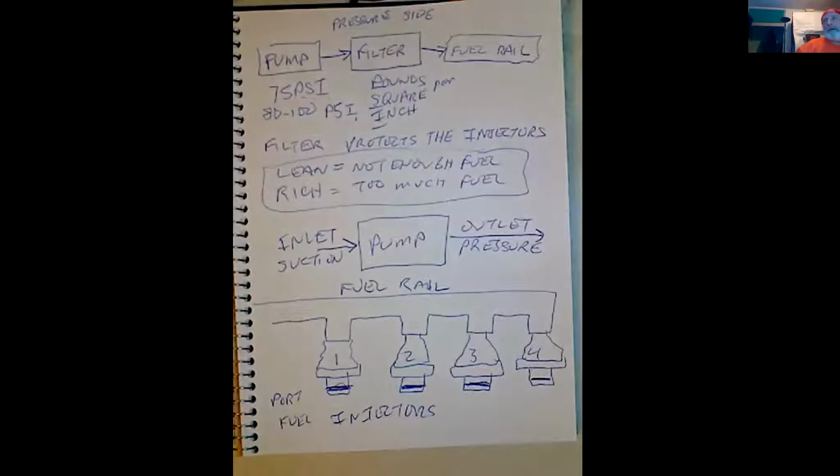Which port? Intake port or exhaust port? Intake. Good. So they're going to be in the intake port, and they're going to be shooting right at the back of the intake valve. Now, what's that going to do to the temperature of the intake valve? No, decrease it. Cool it. Yeah, it's going to cool it down. I'm not saying the fuel's cold. It's probably 115 degrees maybe, depending on conditions. But it's way colder than the valves are.